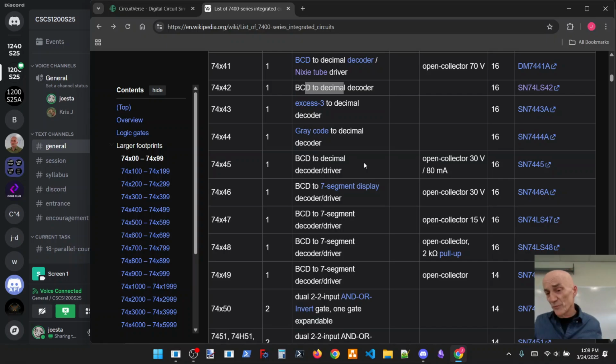So it might look like you're pressing 2 buttons at the same time, but only one of them gets evaluated at a time. Only one can change. So when we're going through the truth table, instead of doing our regular counting of 0, 1, 2, 3, 4, 5, we thought about it in a different order. Because what happens when you go from 1 to 2? 2 bits change.